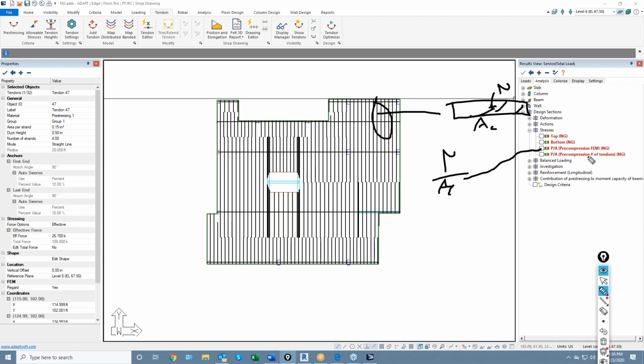That could be a little bit tricky because if the slab and the layout of the walls and the supports was in such a condition where you actually started to develop in-plane restraint, then you would see a huge drop off in pre-compression. And some users would fight that. They would say, well, we know we're going to detail the slab to release the slab and allow it to shorten, or we might have pour strips or a combination of those two things, but the program doesn't really simulate that.